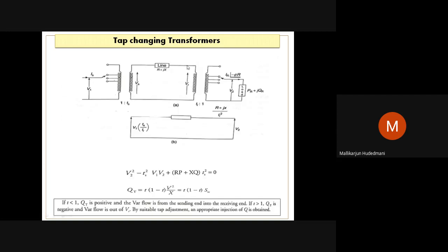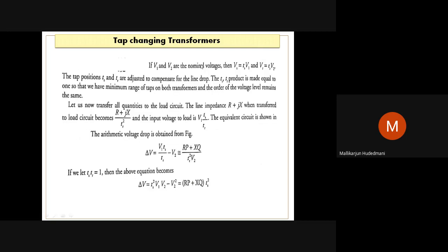Voltage at the transmission section's entry point, the sending end point, is whatever the voltage I have here via the transformer 1:Ts. I am shifting it here. I can convert this. What is the voltage available here? Voltage available here is Vs. Vs is V1 into Ts. When I take a ratio of this, I can convert by the transformer approach. I'll be getting Vs as V1 into Ts.